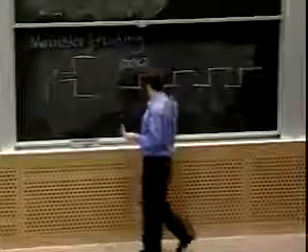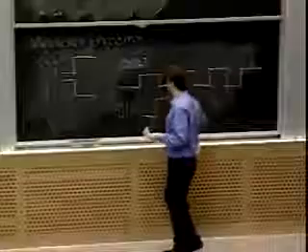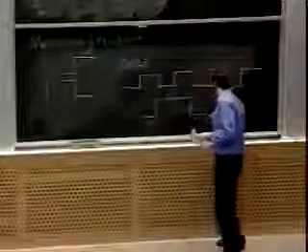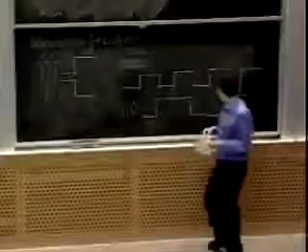And if I transmit the signal 0, 1, 0, this is a transition from low to high, followed by a transition from high to low, followed by a transition from low to high. So now we have a way to guarantee that every bit has at least one transition in it. That's going to allow our phase lock loop to lock into the phase of the signal that's being transmitted. Of course, the cost of this is that every bit has a transition in it.